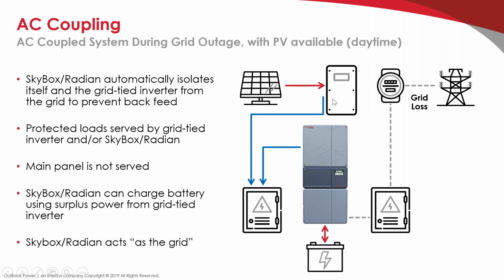60.5 hertz. If this is an old UL 1741, IEEE 1547 inverter, it's just going to shut off at 60.5 hertz. If it is a UL 1741 SA compliant inverter that has grid support functionality, as we increase the frequency in California Rule 21 up to 62 hertz, it will start curtailing its output, which will keep our battery from getting overcharged. So we use this frequency-watt functionality of the 1741 SA, and we'll just keep cruising along here.